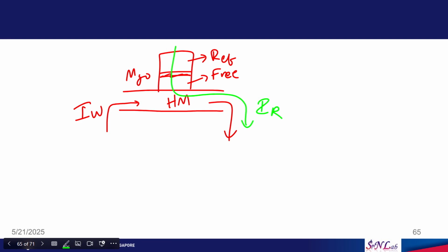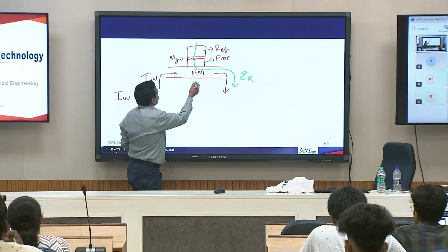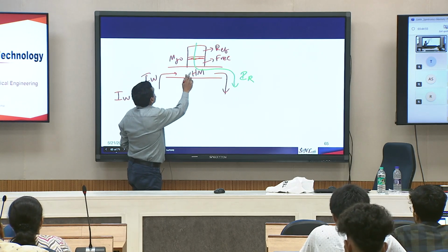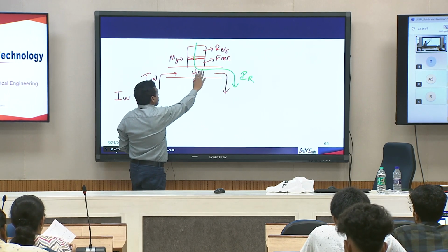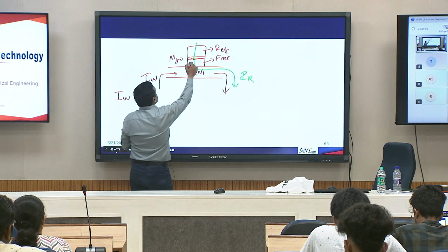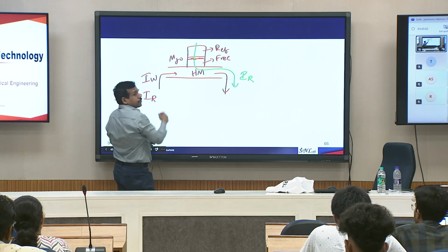Okay. So, for reading you are using another path, for writing you are using a different path. So, the writing current is larger than the read current, right. But the larger current is now not going through this device. It is going through the heavy metal. Heavy metals are usually reasonably good conductors, so they pass the current relatively without much problem, and this tunnel barrier does not break.